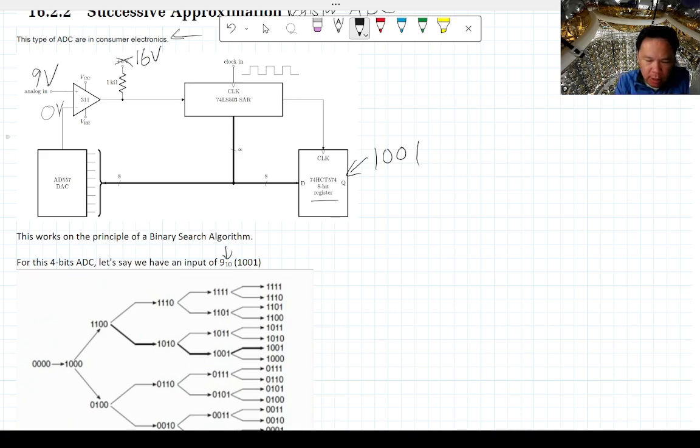Okay. So, well, obviously 9 is bigger than 0. So this comparator gives you true as the output. And that output gets sent over here. So this is just a pull-up resistor to keep the voltage high. Oh, I don't want that, that's going to be too high. Let's keep that at 5 volts. Okay, so that is correct. It's going to pull it up so you have 5-volt TTL logic, most likely.